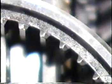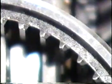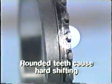The synchronizer ring also has beveled points on its teeth that match the beveled indents inside the coupling sleeve. These points assist in aligning the synchro ring with the coupling sleeve. If the teeth on the synchro ring are rounded by wear, it could take noticeably more force to slide the sleeve over the synchronizer ring teeth and make it difficult to shift into one specific gear related to that synchronizer ring.